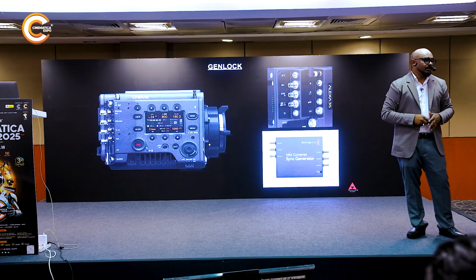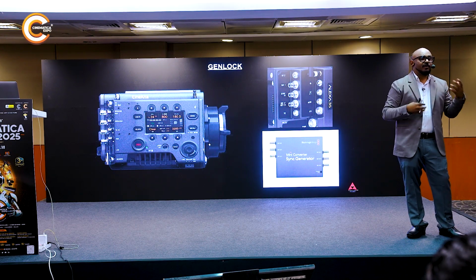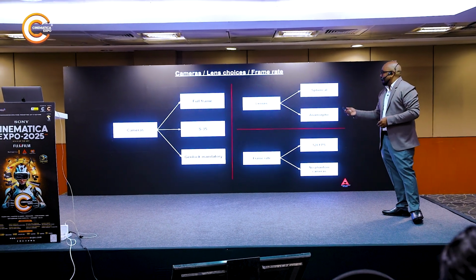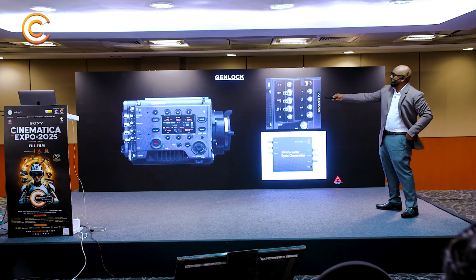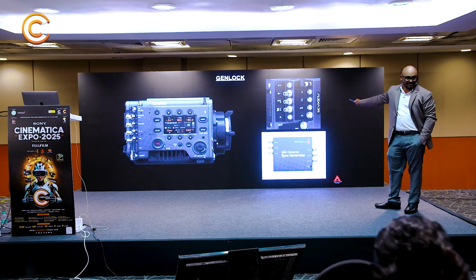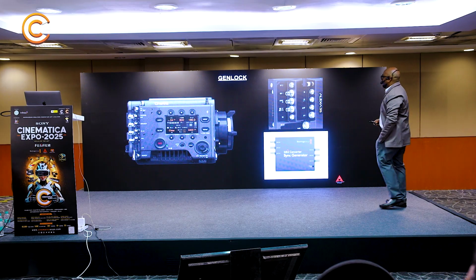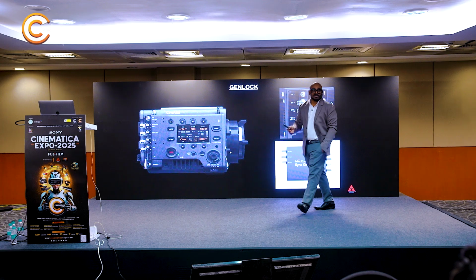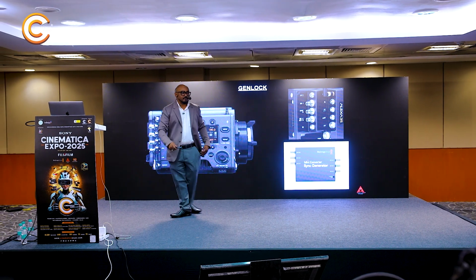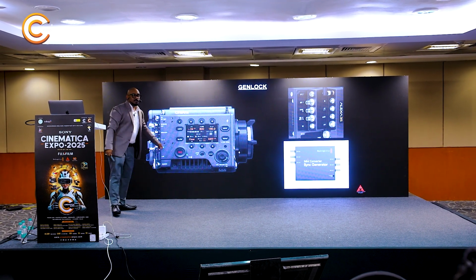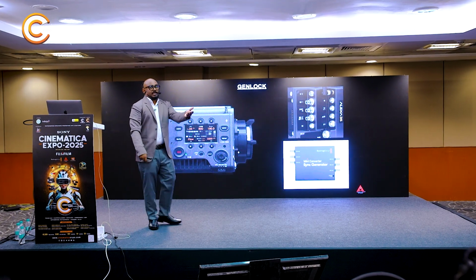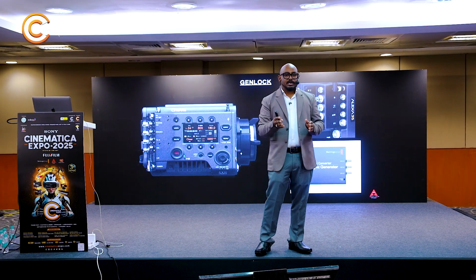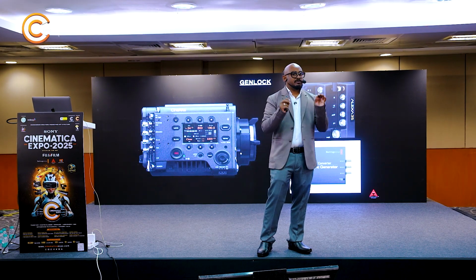So Genlock is mandatory. Otherwise, you might face different issues while shooting. As an example, that's a Sony Venice 2 here, and this is an Alexa S35. In some cameras, the Genlock port will be mentioned as sync in, and in some cameras it will be written straight away as Genlock. Here, this port. You can search any camera's data on Google, and it will tell you whether that particular camera has Genlock or not. So this is very important.